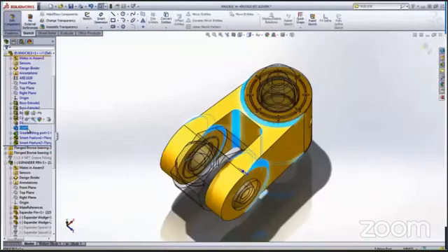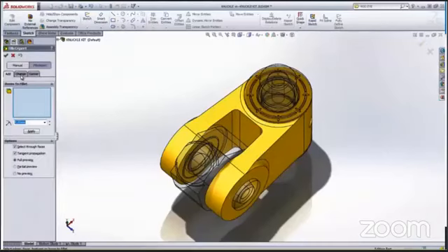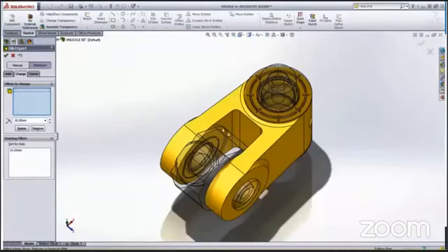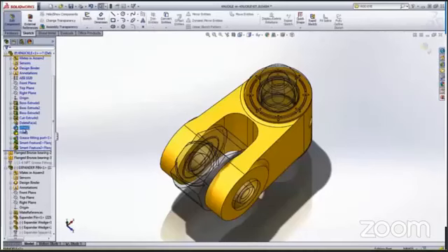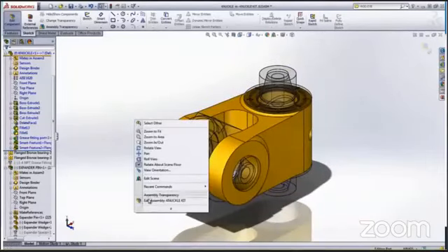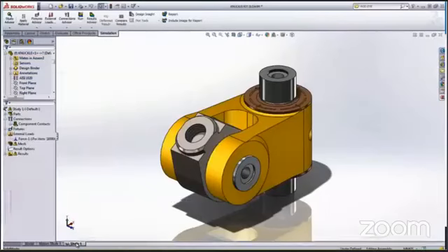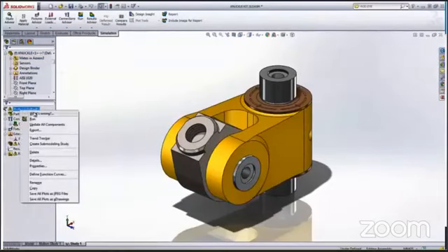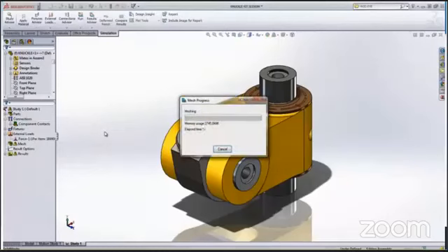So we are going to need to make some changes. With SolidWorks, there is no need to start over. Just edit and make some changes that will strengthen the area of concern. Here we will modify the fillets, apply the modifications, and automatically when the part is updated, the whole assembly and the drawings are also updated.